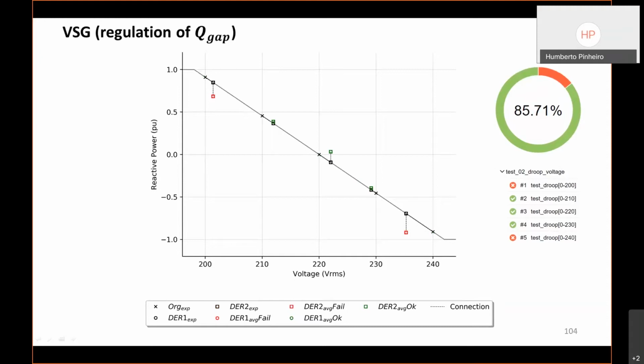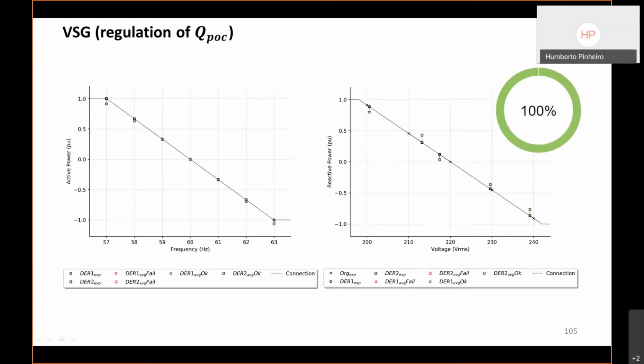The reactive power that is measured is at the POC, since the reactive power that is regulated is computed using the electromotive force. So there is this difference associated with the virtual inductor. If you move the point where you measure the reactive power, this drawback is solved.